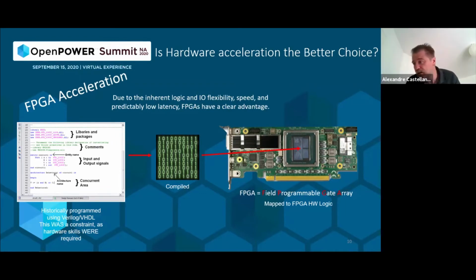Today, once you have synthesized the design, people would say compile, but it's a synthesis. Think about a compilation. Then you can get a binary file that you store in the flash memory, which allows you to program the board when you begin to power up your circuit.